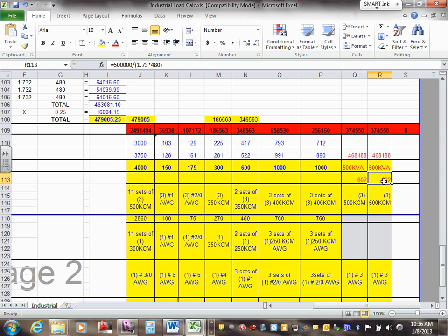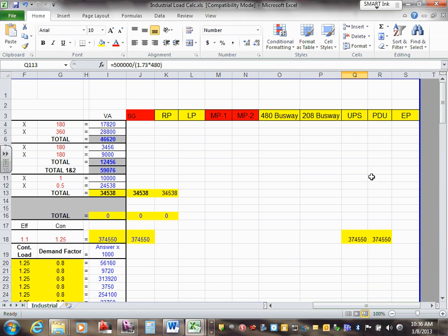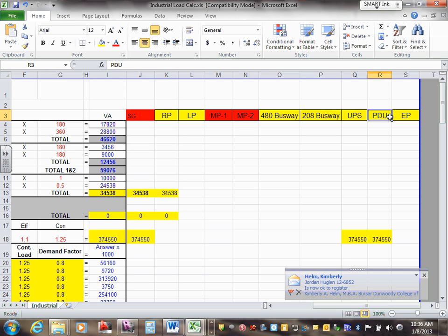Okay, so I end up with these amps. The PDUs and the UPSs are sized based on KVA. The reason why I need the amps though is because I need to size the cables. When I get the amps, then you can size the cables based on this value. Later on, so these are probably the least experience that you guys have, UPS and PDUs. Just use my numbers for the time being, and I'm interested in the KVA, and then I have tons of calculations we're going to be doing about UPS and PDU sizing. I know we haven't done that.